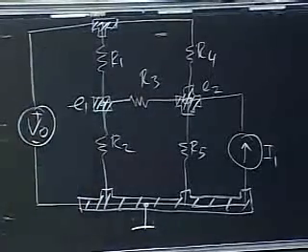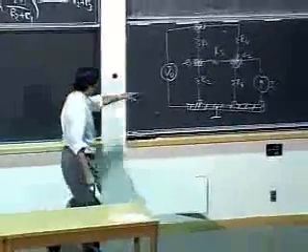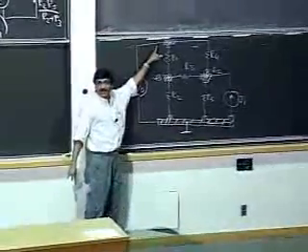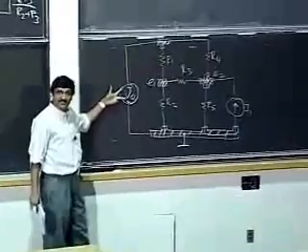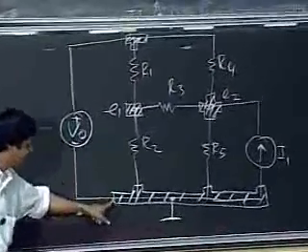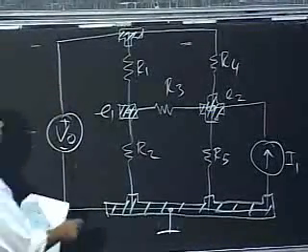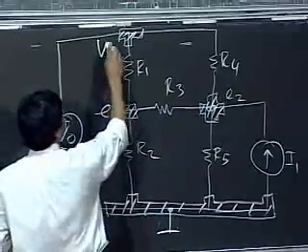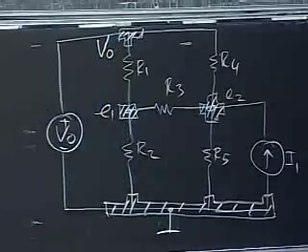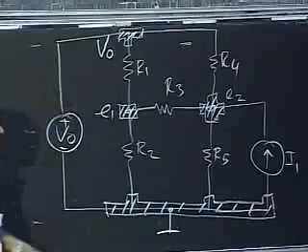What about this one here? Is that voltage unknown? No, I know what the voltage is because I know that this node is at a voltage V0 higher than the ground node. Okay? Notice that to go from here to here, I directly go through a voltage source, and so this node has voltage V0, and I'll simply write down V0. Okay? If you try to simplify the number of steps that you have to go through, so directly go ahead and write down the voltage V0 for that node.